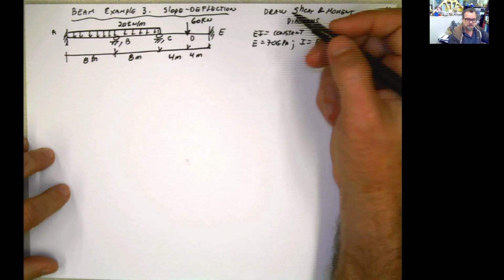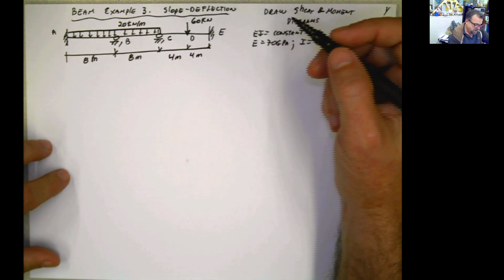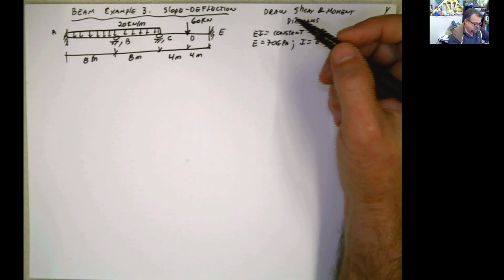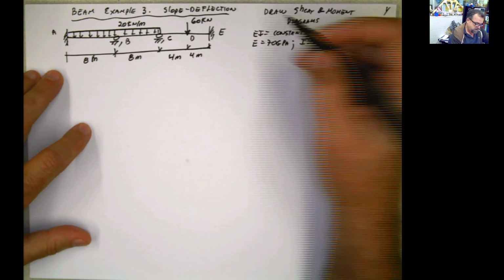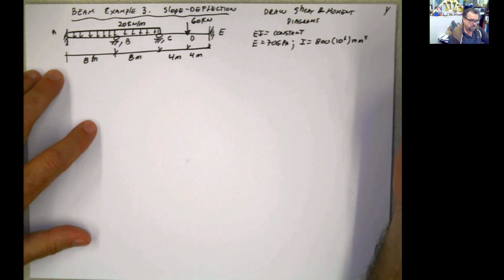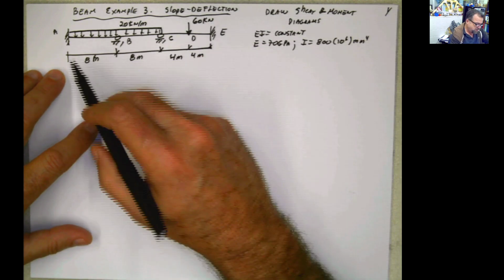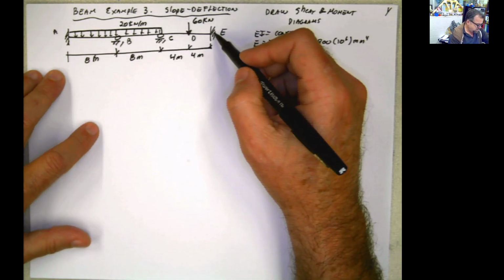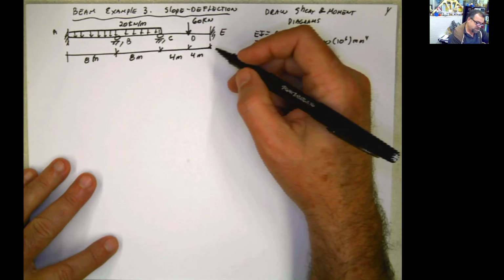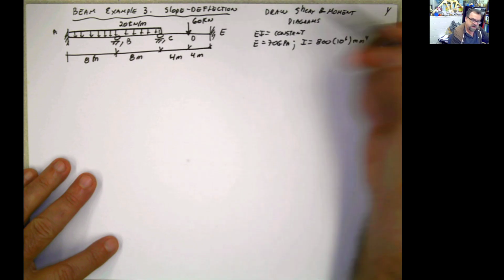In this case we don't have pins and rollers, and if you realize, the degrees of indeterminacy are more in this problem. In the other problem we have only 1 degree of indeterminacy. Now you have 3, 6 here, 7, 8, 8 minus 3, 5. This is statically indeterminate of the 5th degree.